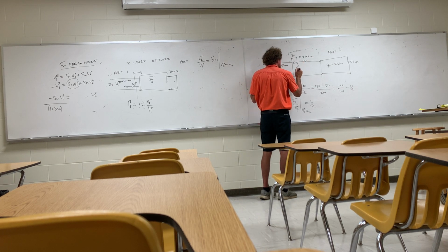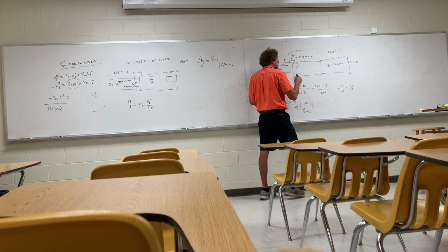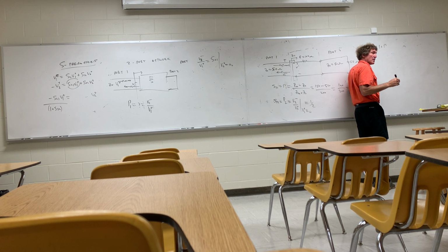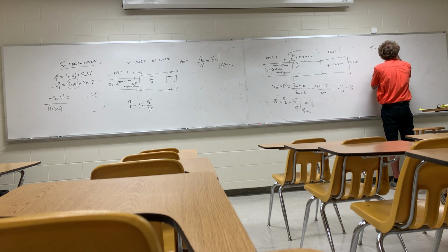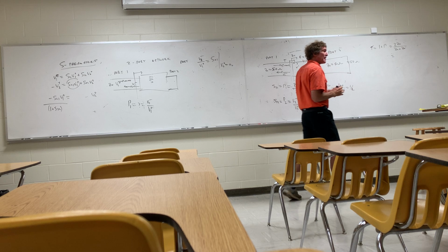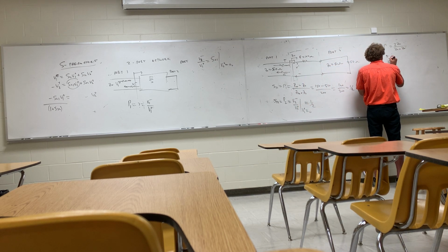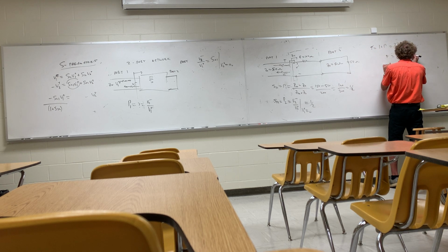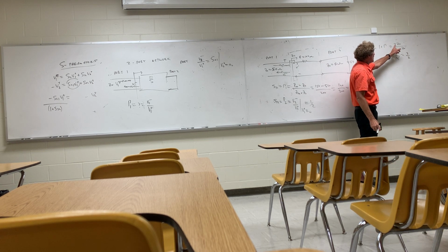So what I need to do is get the transmission coefficient right here. I need tau. And the transmission coefficient, you can get it by saying it's 1 plus the reflection coefficient, or you can say it's 2 times the impedance you're going into over the impedance you're going into plus the impedance you came from. Either one of these two will do it. Well, for my case, I have a reflection coefficient at port 1 equal to 1/2. That means we can do it both ways: the actual transmission coefficient, which is the ratio of V prime over V1 plus, will be equal to 1 plus 1/2, which is 3/2, and we can get it this way too. Our input impedance is equal to 150, right? On port 1, do you follow me?